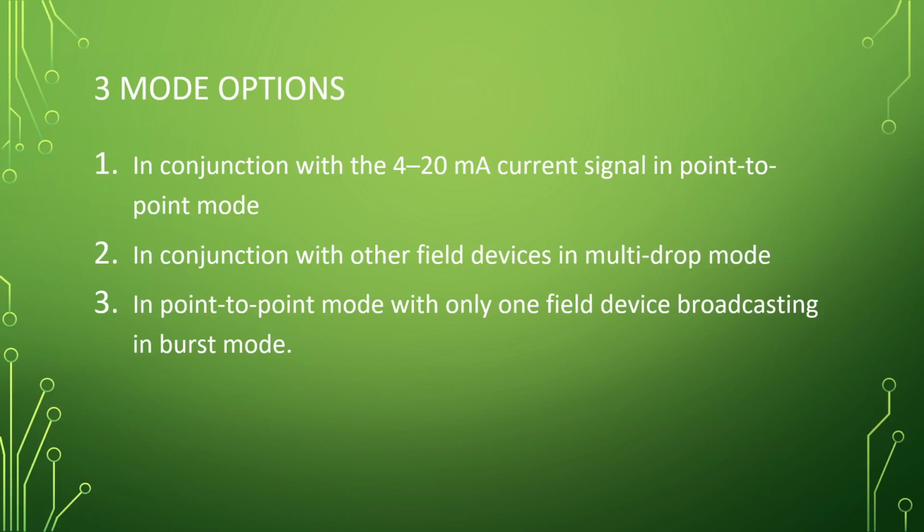All right. So mode 1, that would be your traditional HART analog sensor out there. The main data, the pressure, or what we'll just go with pressure in this instance, is still being transmitted over 4-20 milliamps. So it's still sending out that analog signal, and then for the other information, the HART protocol, the PLC is requesting it, saying, hey, I need this.